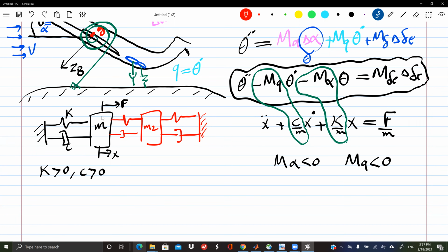Okay, so the black thing is just a single degree of freedom. We know for sure, just having any values of stiffness and damping, the system is stable. It will eventually come back to its equilibrium if you disturb it. Very good. Now, I added more stabilizing elements. So I added more good things. I shouldn't expect any bad thing to happen.